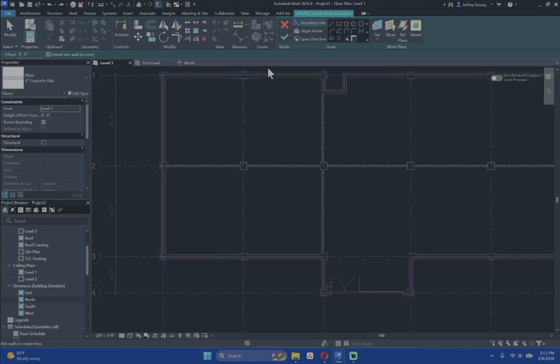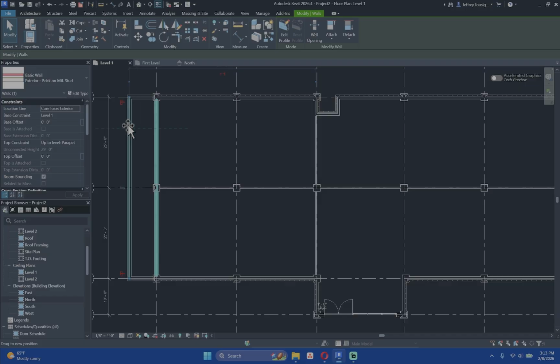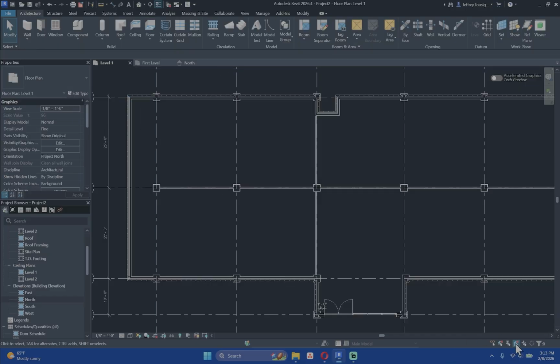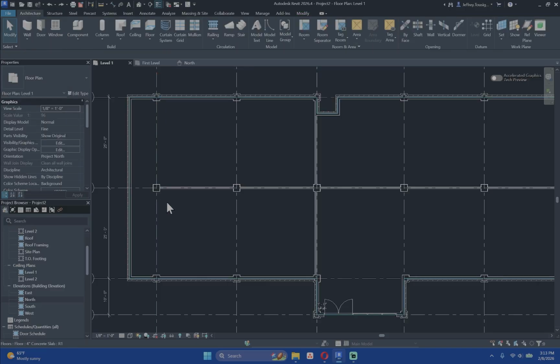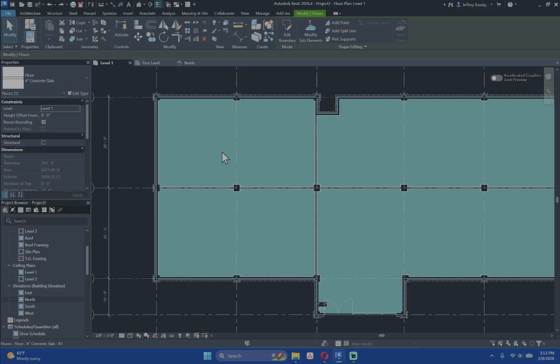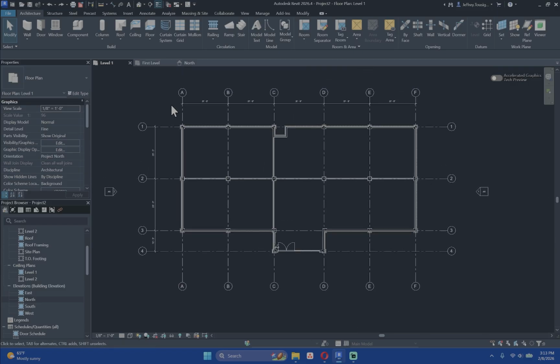When we select pick wall, not just pick line, it is picking these walls. And that means if one of these walls change, it is going to update the floor for us. Maybe not other stuff, not everything, but at least the floor it would. So we can confidently put that in. And that's enough to get you started.